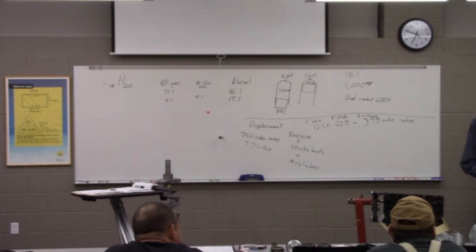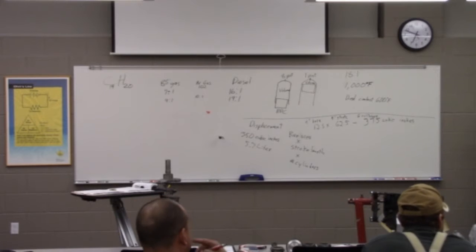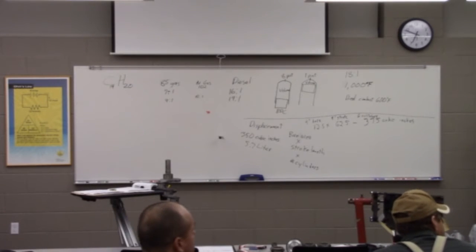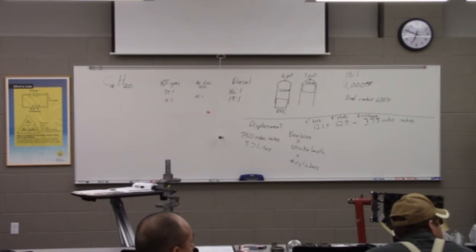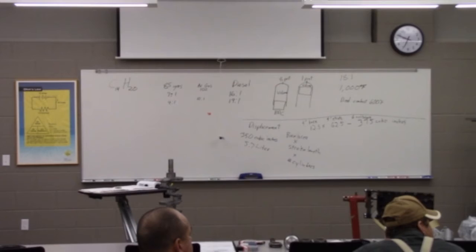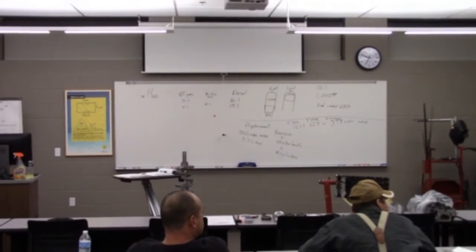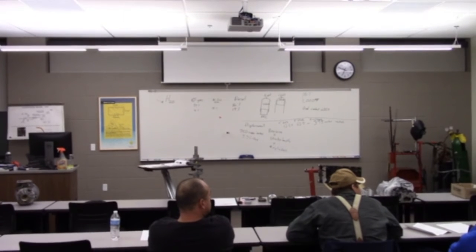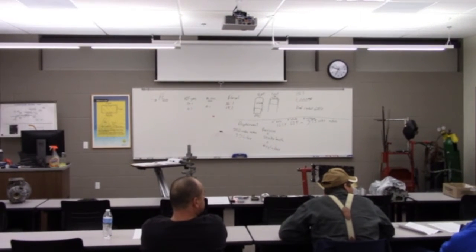So talking about that, I'll pass this around. It's a connecting rod bearing out of one of those 5.9 liter Cummins, and you can see how it's worn through two of the layers and into the third layer. Can I borrow it back just a second, Joe? This shinier layer that you see here is what we started out running against. And then there's a darker gray layer under that. And then underneath that, there's the copper layer. So this one's worn enough that the clearance probably isn't 0.02 of an inch anymore, do you think?